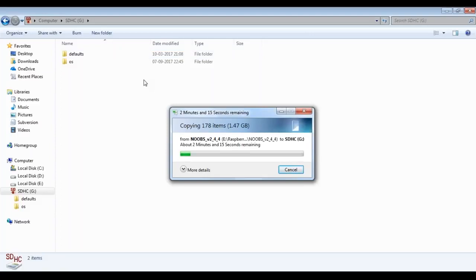Now again, this is why I recommend that you use a high-speed memory card, because if you're not using one, it takes a lot of time to fetch the data. As I had mentioned, if you're going for a memory card for your Raspberry Pi, you can use something like a 16 GB at least, and make sure it has a high transfer speed. This will give you a lot of memory area to work with. I would also recommend a class 10 memory card, which is available in the market today. These have a very good read and write speed ratio. So definitely consider this while you're getting a memory card for your operating system.